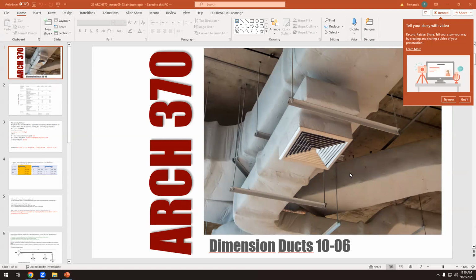because sometimes we have a limit on the building height. If you keep adding different ducts at different layers and making the space between the false ceiling and the slab bigger, there is a moment in which, okay, you cannot build the third floor because you have exceeded the height limit in the municipality or in this area, so you cannot go higher, or your building should be within these limits. If you keep adding space in the false ceiling, you will probably lose one floor.